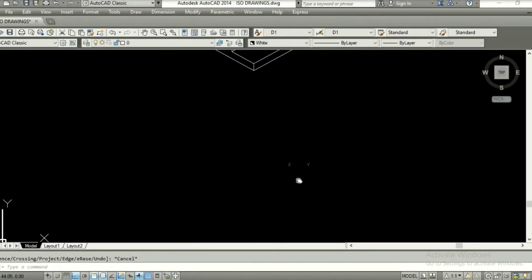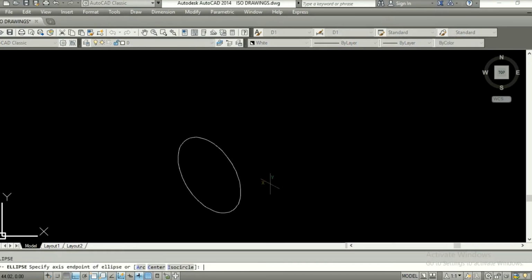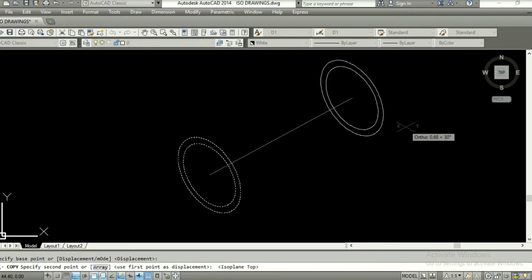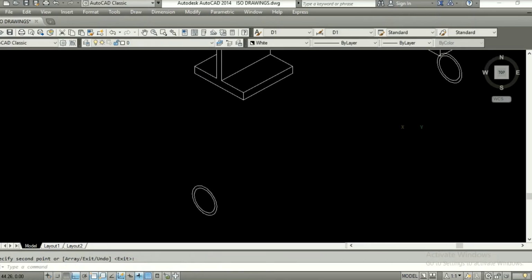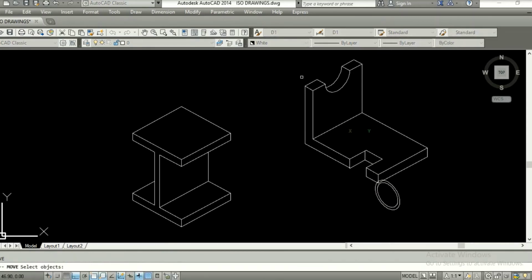Yeah. So again, for this ellipse, isocircle, press F5, diameter 0.3, again ellipse, isocircle, specify the center, diameter is 0.25, yeah, copy, hold it by the center, press F5, 3 meters, there you are. It's gone a bit too far, no problem. We'll just move this object a little bit upward.